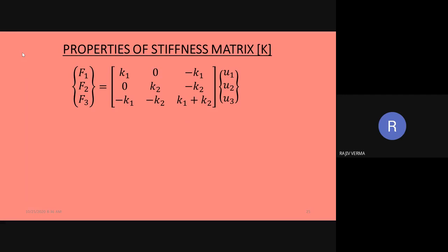We have taken a problem consisting of two elements. Both the elements happen to be linear. Therefore, both elements have two nodes each. And to add to the simplicity, the current example has only 1 degree of freedom for every node, which means that every element has a degree of freedom of 2, which in turn means that there are only 3 degrees of freedom, or you can say 3 unknowns, which are present in the entire solution process.